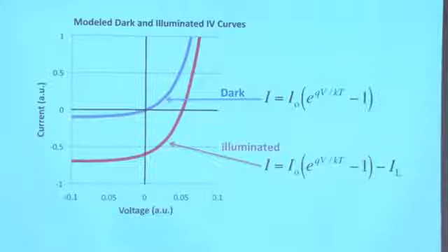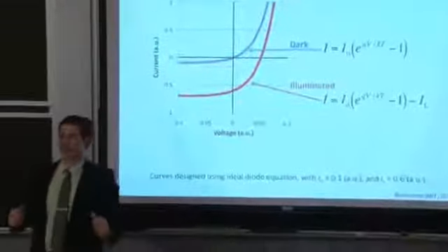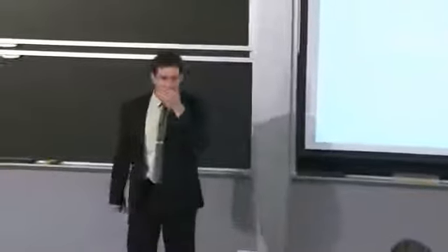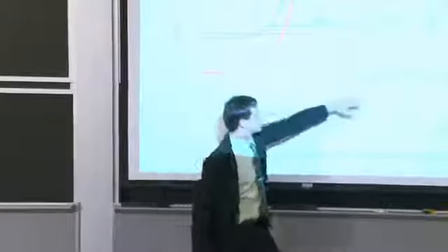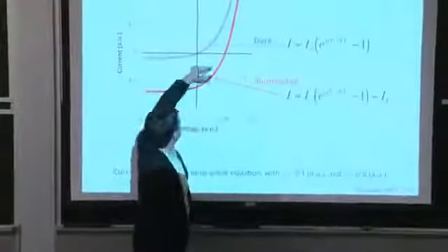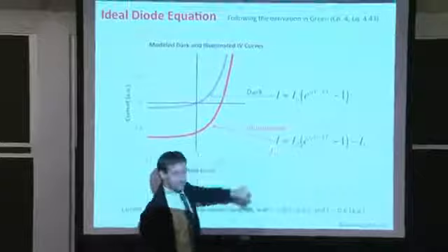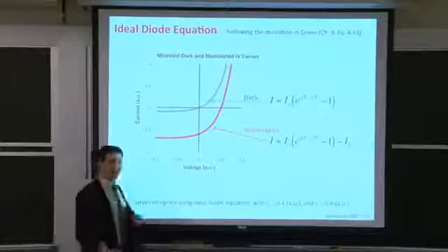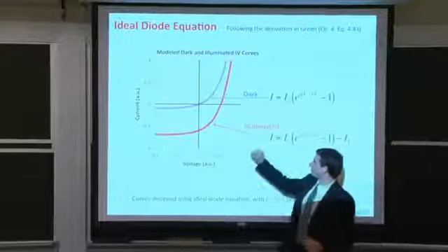All right. What do we think will happen if our light intensity goes down by a factor of 2? So now if the amount of sunlight falling on our solar cell drops by a half, what will happen? What do we predict will happen based on this right here? The red curve will shift up by about half, right? Because the illumination current is now cut in half. What will happen to the voltage intercept right here? What is the relation between voltage and current? It's a logarithmic relation, right? So it won't necessarily be cut in half, but it'll be reduced by whatever this would be here, log of 2.